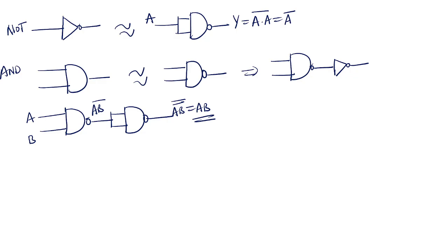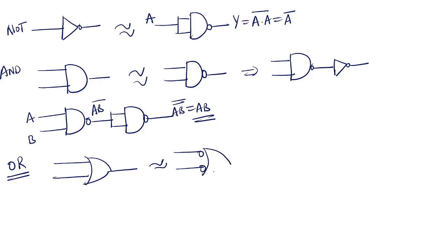This is the AND gate. And coming to the OR gate. For the OR gate, first you draw the OR gate. So wherever OR gates are there, you need to add the bubble at the input. Yes, at the input you need to add. And next, wherever you added the bubble, you need to add the inverter.